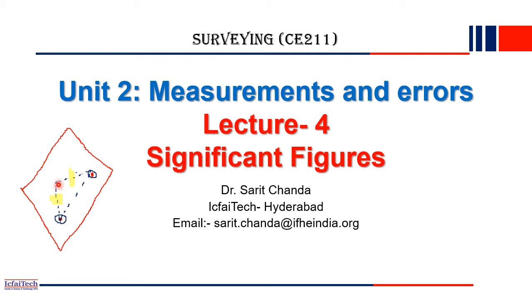So if we can't see directly because of an obstacle in the middle, we can't take that point as the next control point. We have to choose the control point such that there is no obstacle. For example, here this point may be visible from here as well as from here, so this is our next control point. Like that, we initially make multiple control points over the entire area or region.